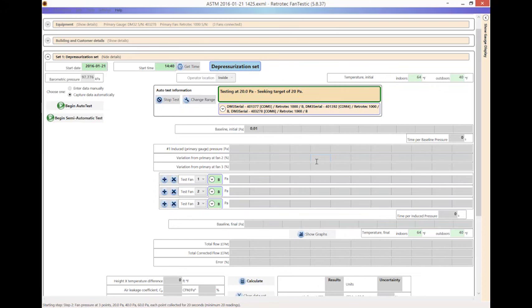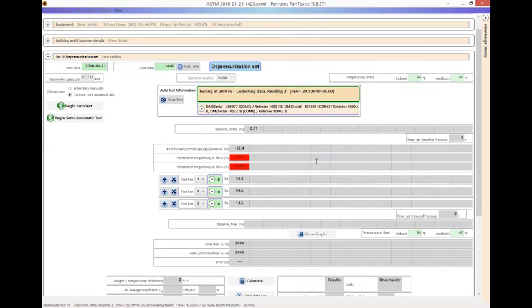So they're all set to the B range. And now they're going to establish the first test pressure, which is 20 pascals. And it's not uncommon that it can overshoot those pressures. So what we see in the red, that just went from red to gray, the top is actually the pressures that are in the room compared to outside. So it says in the beginning, the pressures that you had in your room with the gauge compared to outside were not close enough to your main gauge, but now they actually have fallen into place.